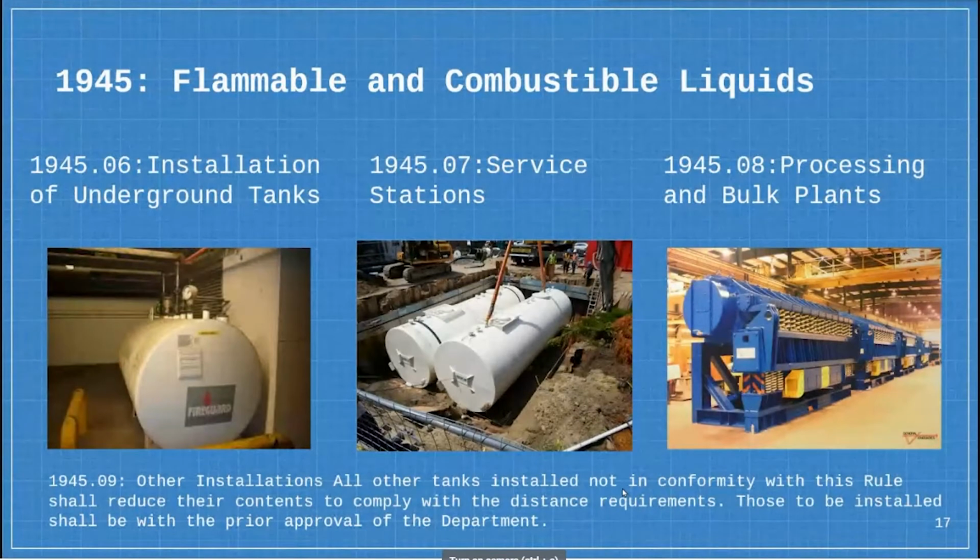So, next, 1945.09, other installations. All other tanks installed not in conformity with this rule shall reduce their contents to comply with the distance requirements. Those to be installed shall be with the prior approval of the department. So, yung ibang naka-install na tanks na di pasok sa rule, dapat bawasan nila yung content.